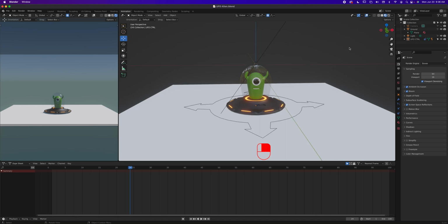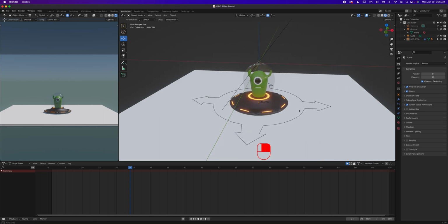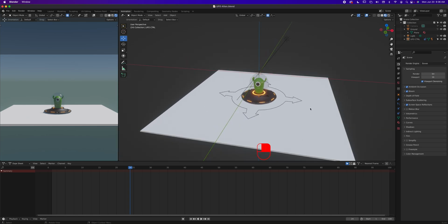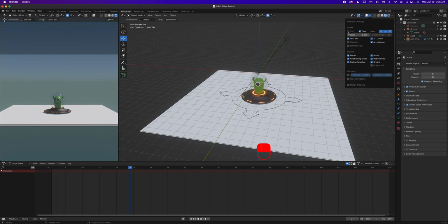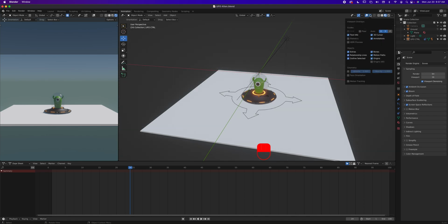Okay, I'm going to turn on my overlay so I can actually see the screen. So what are we seeing on the screen here versus what I turned off, versus the default? If you go to overlay over here, I turned off the floor, which is kind of like the grid line. Grid by default I think is turned off, and I turned on the Z-axis right here. Normally this is the default that you'll see in Blender, but they just kind of cluttered the screen for our demo, so I turned off the floor, but I did activate the Z-axis.